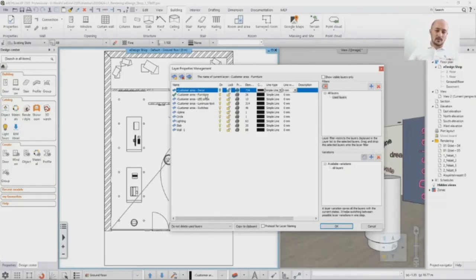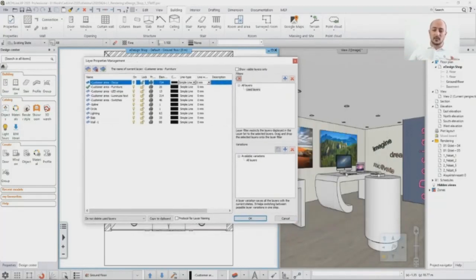The other one are the decorative items, like those tiny things, and even some of these computers and keyboards, mobile phones, and everything else. Those are supporting actors of this model. We need them, but not at the first stage. And finally, one layer should be at least for the lighting. Now, in this case, the designer created 3 different layers because he wanted to control them separately. But if you have at least 1 layer by room for the lighting of that room, then you are good to go already. And you can, of course, make it even more detailed, just as you can see in this case. So 3 layers: furniture, decorative items, and lighting.